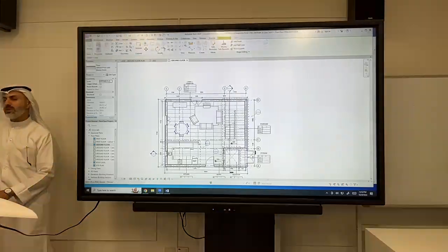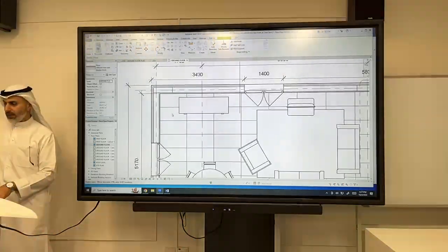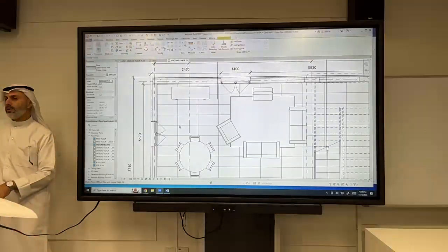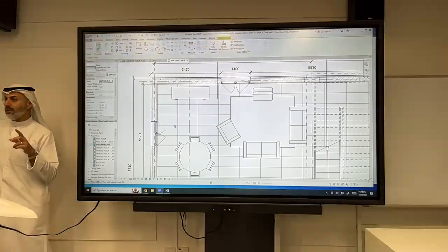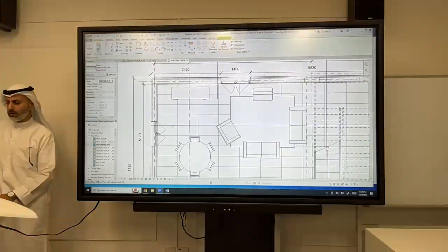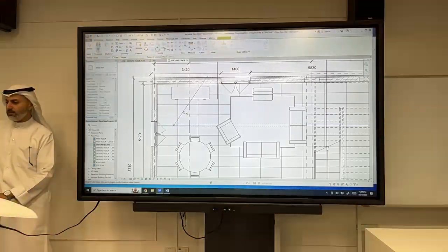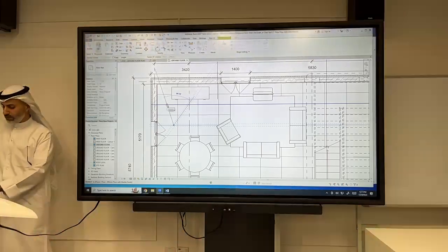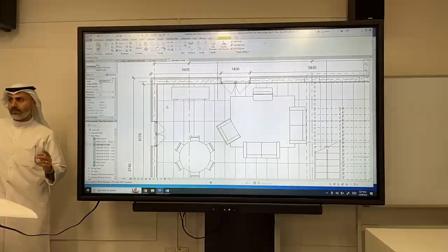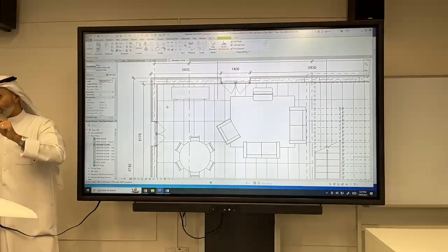You need to find out which is the best wall to align it to. So I'm just using a quick random one. You could also rotate. So let's say now I put it horizontal and you want it vertical. Tab, select either the vertical or horizontal. RO or click on rotate. Click rotate, say you want it 90 degrees. I rotated the pattern vertical. Yes, but make sure you're selecting the line, not the floor. The line of the pattern.